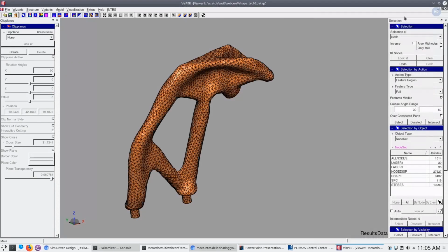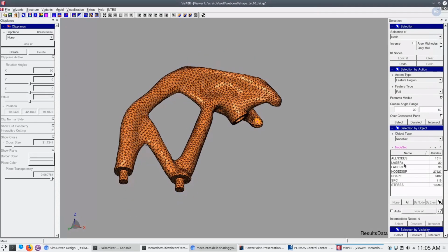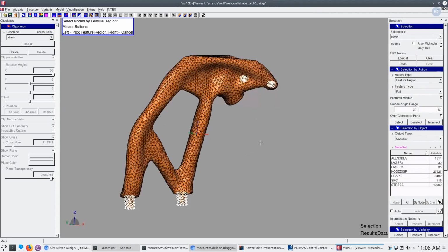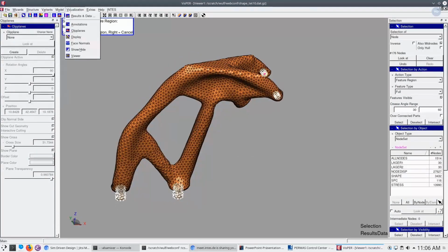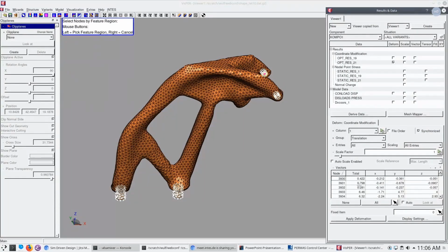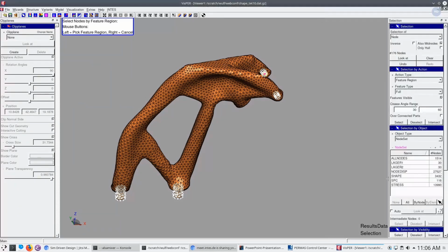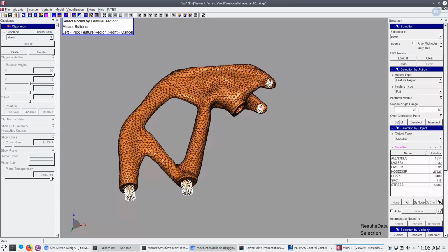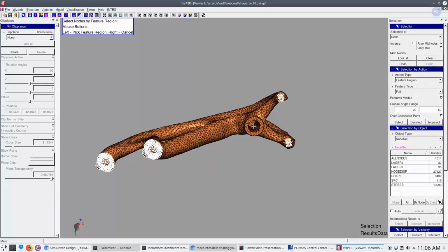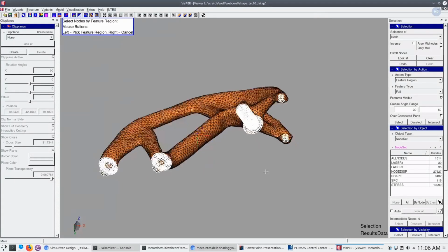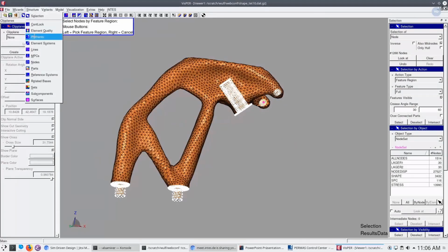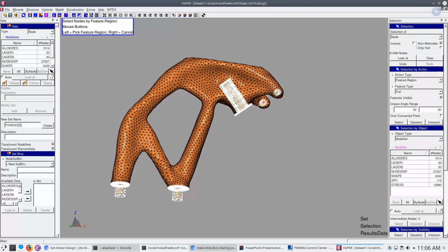Okay, first we need to create the fixed boundary nodes. This is the same as before. I choose the areas of loadings and SPCs and the plane. So I choose this. And then also, no, first, sorry, I have an error. I go back to the visualization. First, what I have to do is to fix the deformation. So this means to fix the shape change done by optimization. Now this is, let's say, frozen. So now I choose here these plane areas. And also again the cylinder, and maybe here the surface. Create a set again. Name it again fixed nodes. Okay.